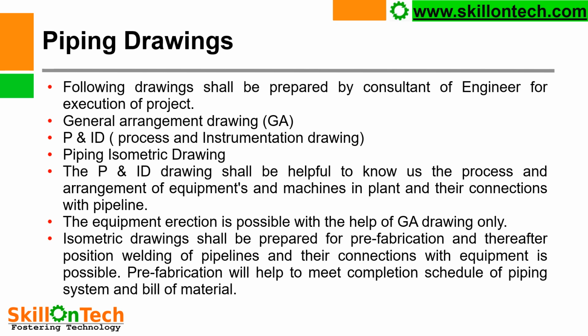Isometric drawing shall be prepared for prefabrication, and thereafter position welding of pipelines and their connections with the equipment is possible. Prefabrication will help to meet the completion schedule of the piping system and bill of material. And after completion of the project, we have to make as-built drawings.